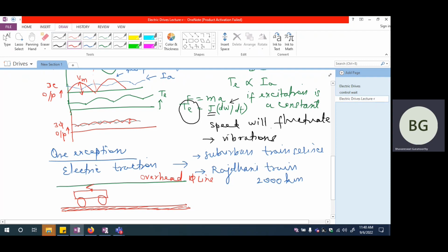And you are going to have the train essentially running between these two. And you will have generally a conductor which is collecting electricity from here. So these are the different units of this train, and they are all collecting electricity from the overhead line. So in this particular case, if it is single phase, you need only one conductor to carry electricity throughout this 2000 kilometer. But if it is three phase, you will require three conductors minimum to carry three phase electricity through this 2000 kilometer. So single phase results in saving of copper conductor. Whereas if it is three phase, you definitely have to incur a lot of expenditure on installing this three-phase transmission line throughout this 2000 kilometers of distance.